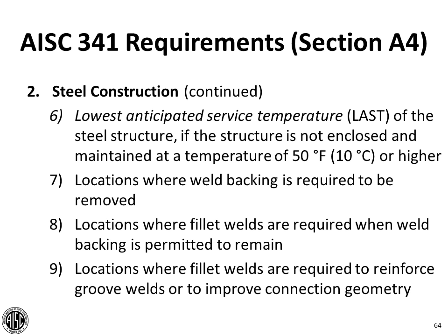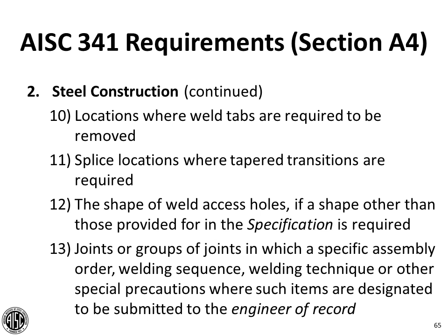The idea of the 50-degree Fahrenheit limit, above which you don't need to worry about it and can just rely on the basic requirements, is really to identify what we might consider to be conditioned environments. And so in these colder environments, there are some provisions that need to be made, and the engineer of record, again, is the one who is required to make that designation. Some of these other items I will illustrate through some of the details, so I won't go through them here. Larry has already talked about them a little bit.